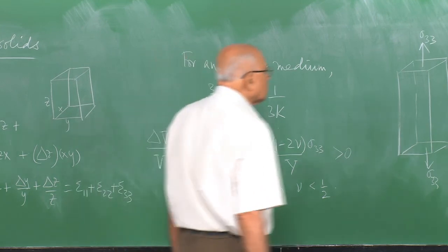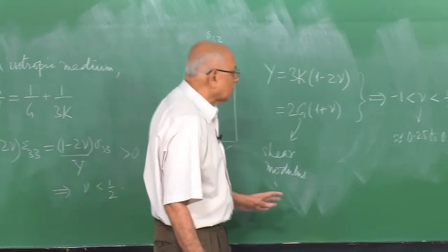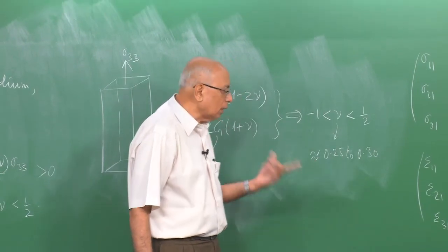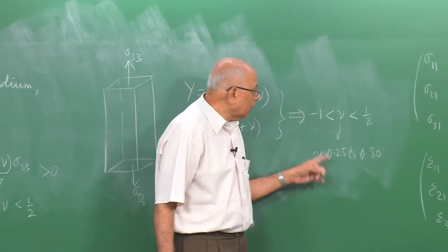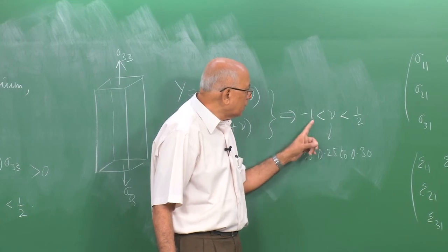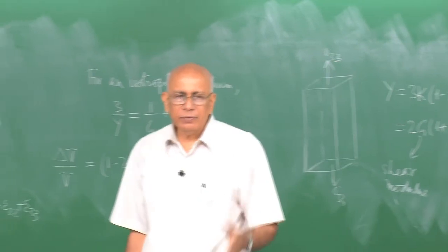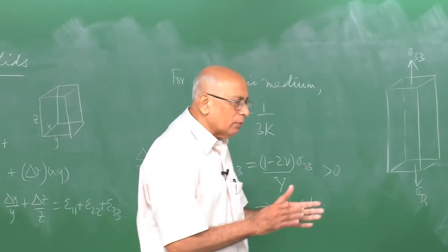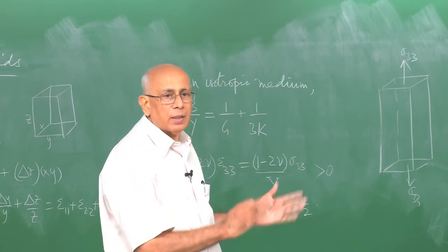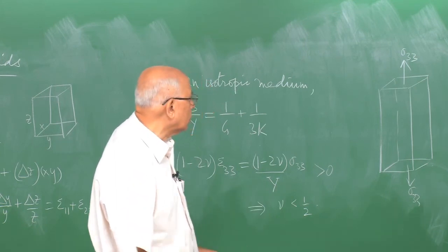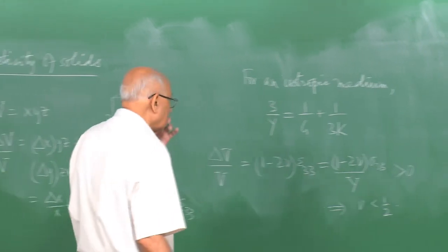But in most normal circumstances, Poisson's ratio is indeed between 0.25 and 0.3, and one can show with a little bit more work that between -1 and 0 you have one class of materials, between 0 and 1/5 you have another class, and between 1/5 and a half would be the traditional class of simple materials for which linear elasticity theory holds in its present form.